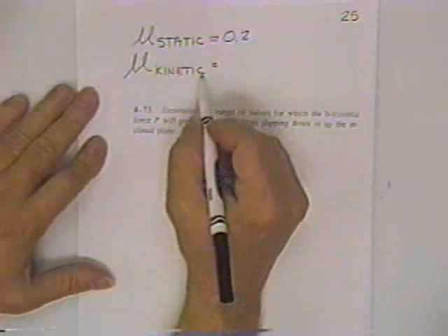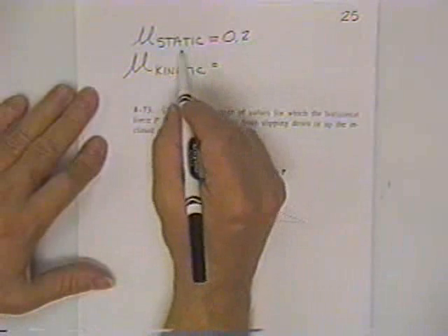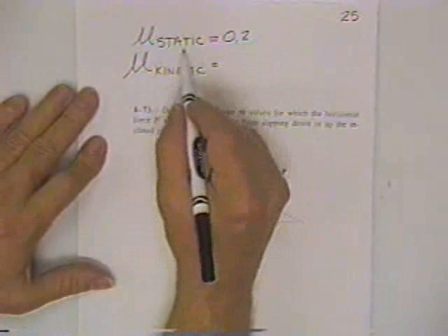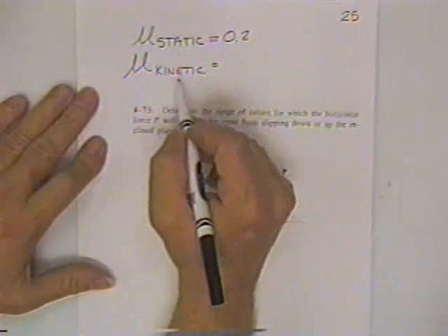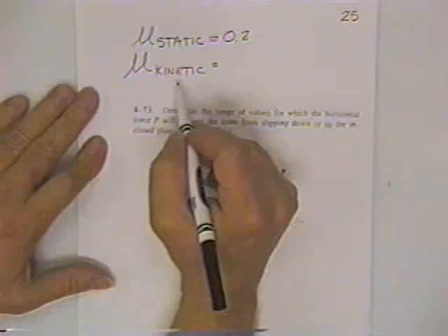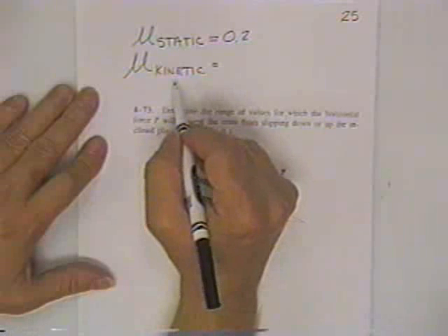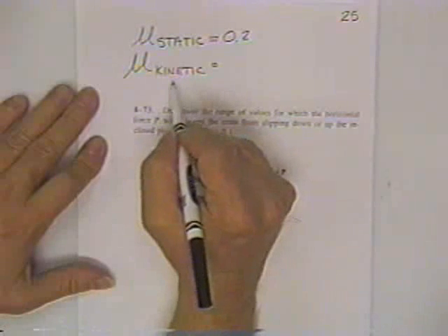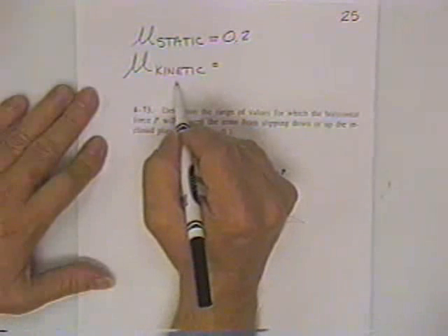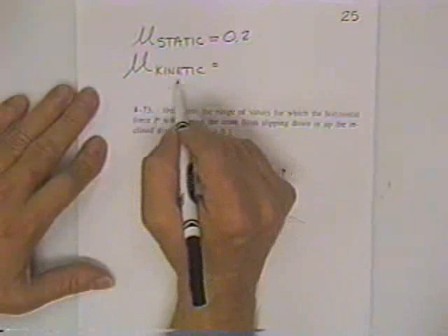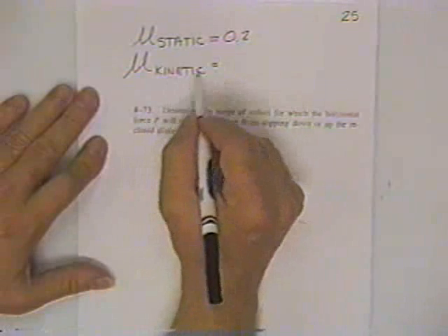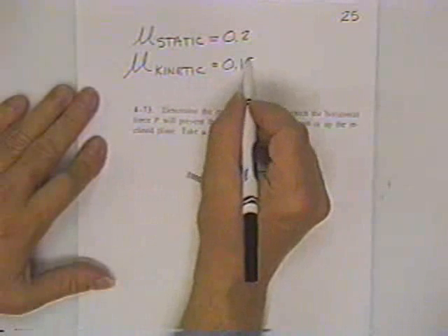That's the coefficient of friction it takes to break it loose. Once you get it moving, the little raised spots and indentations and imperfections that used to be kind of locked together are pretty much dynamically rattling across each other, and so this number drops maybe to this.